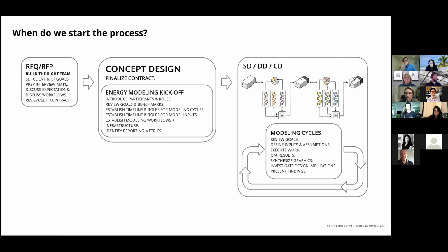And then another step, once you have the project going and you have your team members, is to perform an energy modeling kickoff. And this has been extremely beneficial where once we're up and running with the project, we assemble as a group and we review these items that are bulleted. We talk about the timeline, the goals for the model, what iterations we're doing, how many iterations we're doing, what modeling software is being used, what workflows the consultant is open to, what they've done in the past, what's been successful, where we can find opportunities to improve upon that.